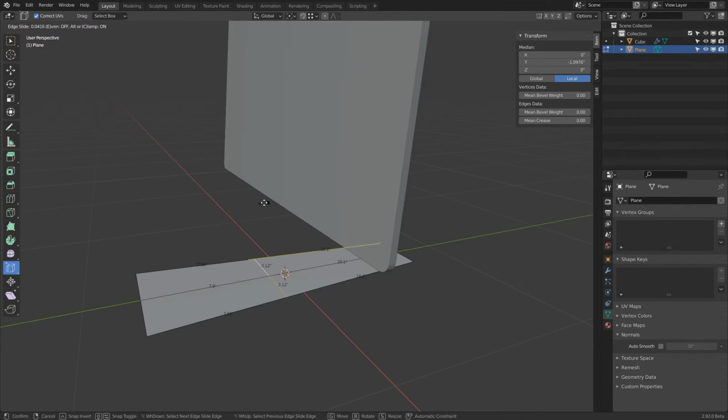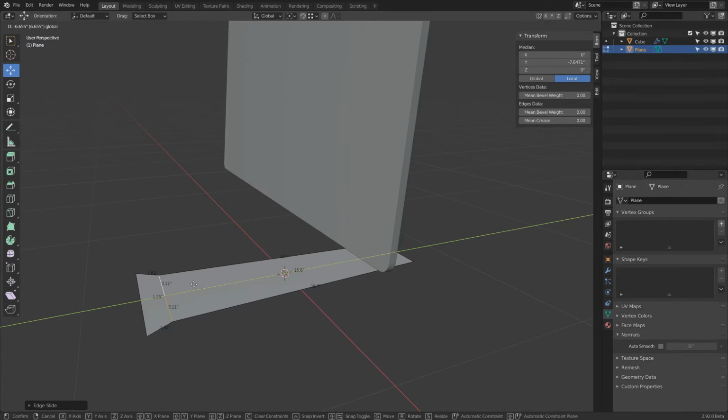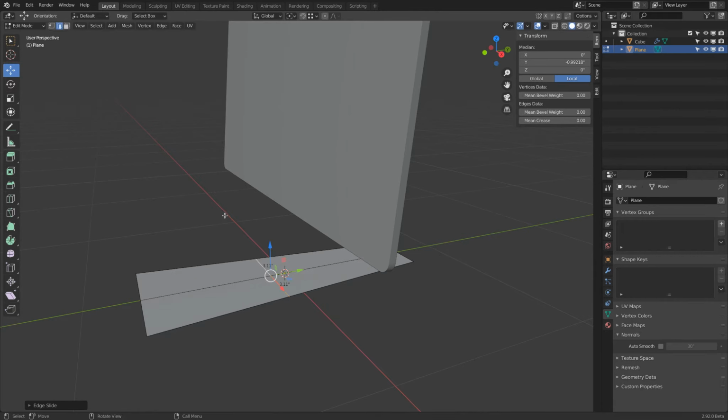And we can slide it, and then you see how the numbers are updating. There, 8 inches. If you don't want to use the command, we can actually, well, we cannot use G, no? Because you see G deforms the mesh, but when you type in GG, so twice, you switch from move to slide. And then this is a very easy way, holding shift, and then we can try to, if it works,